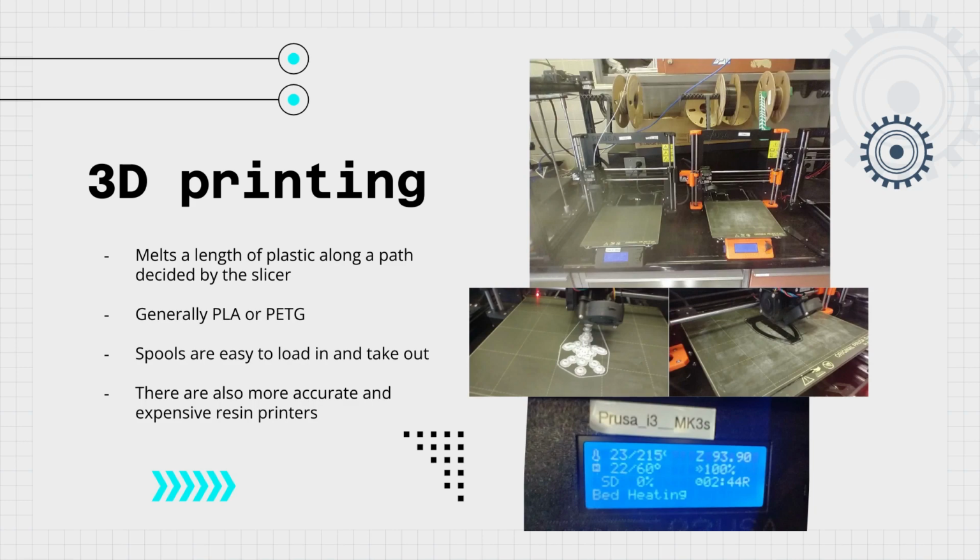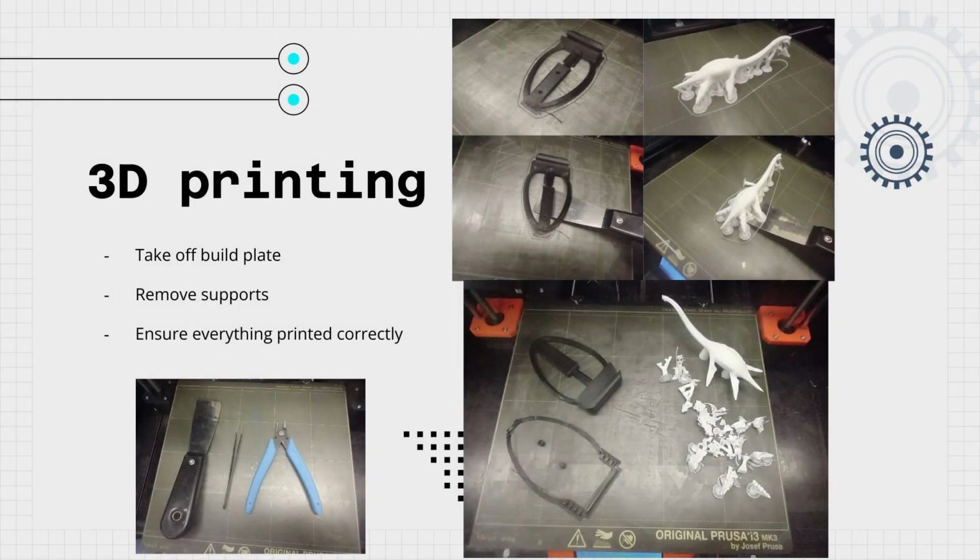And so we have gone ahead and printed. And now we will be using these tools to just take these prints off the bed and then remove all the supports. Generally, removing supports is pretty simple, though these blue plier shaped tools are really good for just snapping off supports that you find difficult to remove.